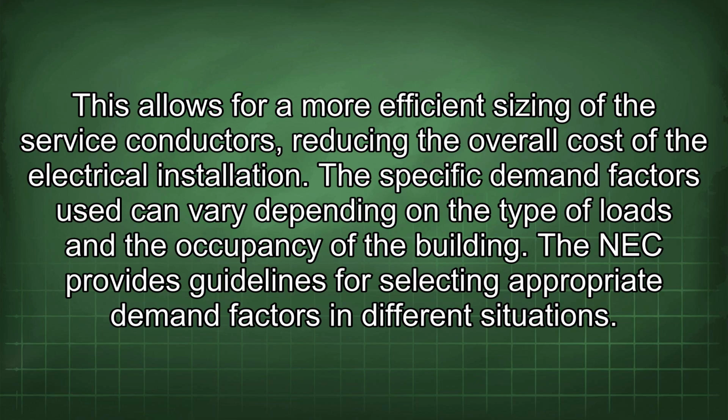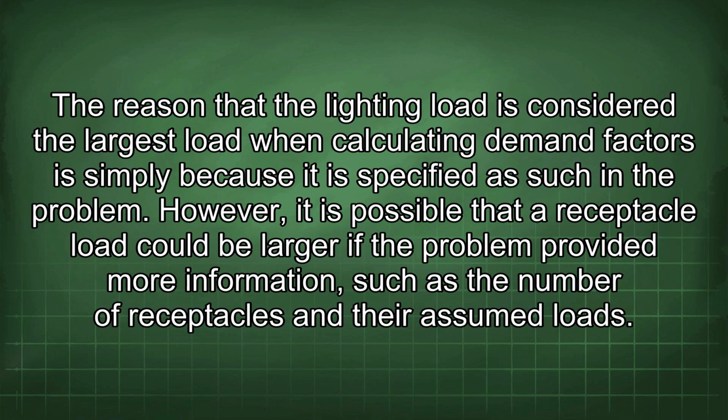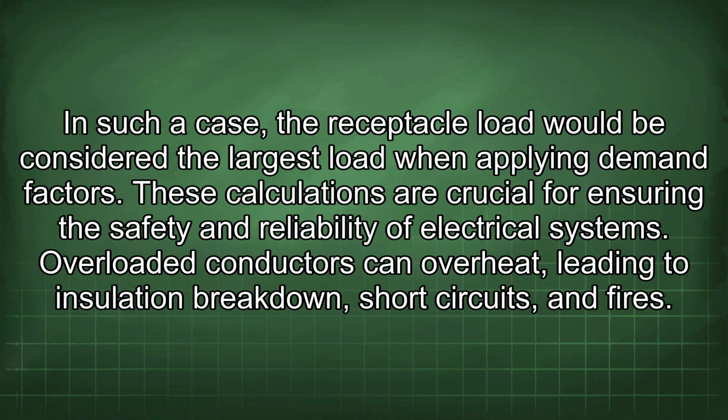The specific demand factors used can vary depending on the type of loads and the occupancy of the building. The NEC provides guidelines for selecting appropriate demand factors in different situations. The reason that the lighting load is considered the largest load when calculating demand factors is simply because it is specified as such in the problem. However, it is possible that a receptacle load could be larger if the problem provided more information, such as the number of receptacles and their assumed loads. In such a case, the receptacle load would be considered the largest load when applying demand factors.